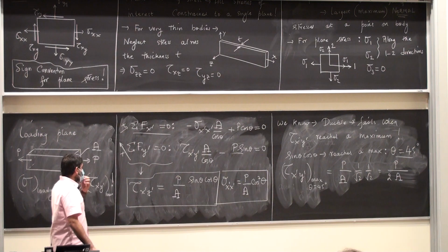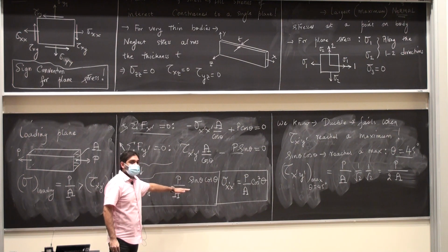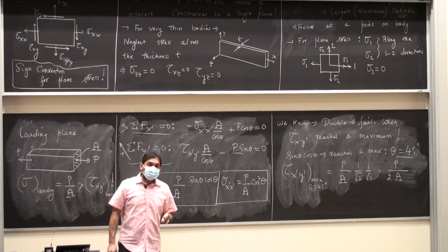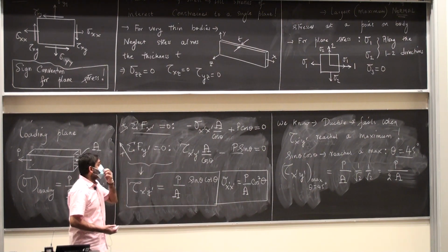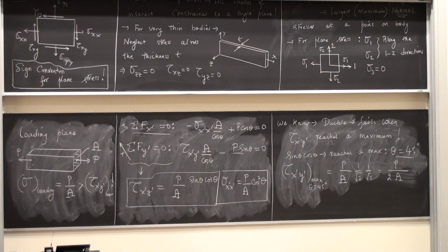And using the experiments, we can design a certain amount of theory. This is highly watered down stuff. But I hope it conveys the point that when materials fail, if it's a ductile material, there is going to be a certain value of stress at which it fails. This is the maximum shear stress value, which is why we are looking at maximum in-plane shear stress. I wrote it down somewhere.